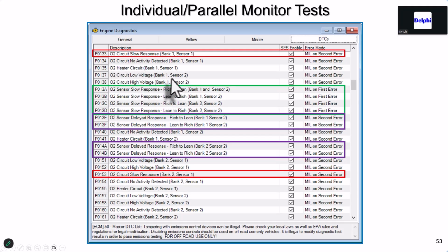They run, and then the computer goes down the list and says, check, check, check, check. Oh, the O2's at this point. Oh, the cat criteria came up. There's enough O2 information over here to go judge a cat. They'll go over and judge a cat, and then they will come back over to the other side, and whichever one of these tests in here for that car is needed to finish it off, that's where the decel comes in. So like that Nissan I showed you, the cat ran first. Then I needed a delayed response to finish it off. The other O2 tests had already populated. And again, I'll show you that in mode 6 in the next class.